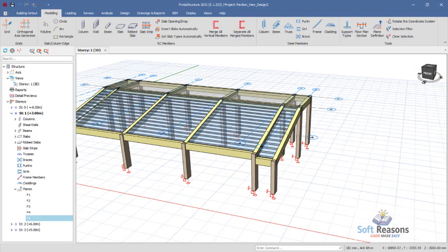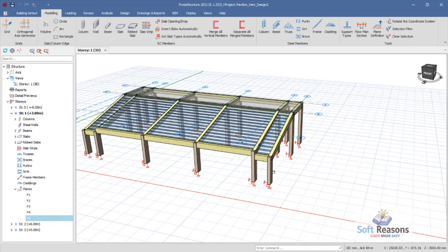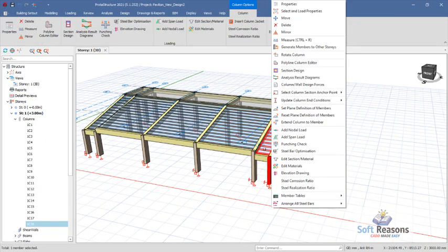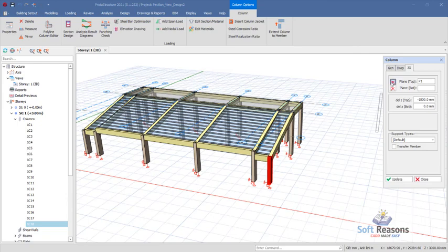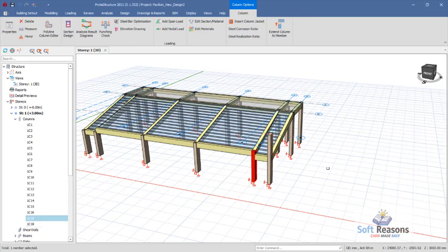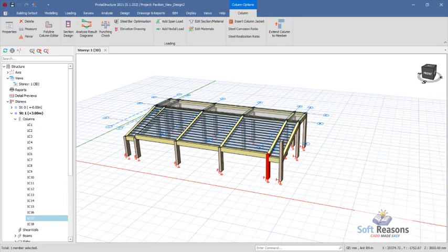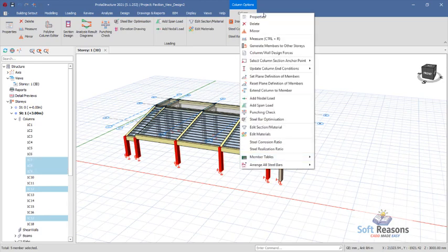All right, but before then, let us work on the reinforced concrete column. Select this. We wouldn't want it to move with the sloped plane. So click on its properties, come over to 3D right there. You have to cancel that slope, update this to take this column back to its normal height. Right, so the same thing is applicable to this, but you can select all of these to ease the working experience, using the control key. So you can select multiple reinforced concrete columns, right click, select its properties.